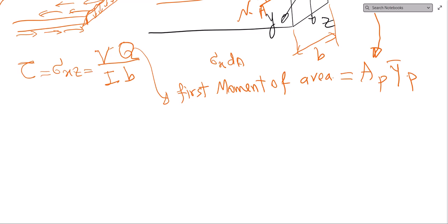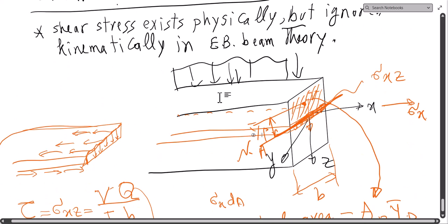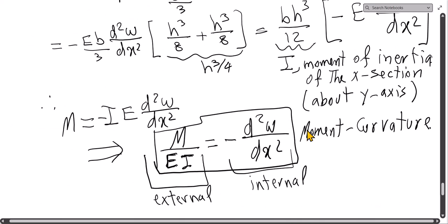I hope this helps you to understand beam theory in general, starting with Euler-Bernoulli, which is heavily used in practice, and sometimes it is not referred to by name, but when we say calculate the beam, we use this theory for calculation, mainly using the moment curvature, and for shear, the explanation that we had at the end. And therefore, we can calculate the deflection.